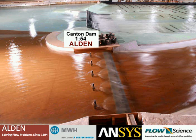We validated that model with a physical model, or better said, we tested our final design with the physical model, and you can see a picture of it here. It's a fairly large model, and this might go back again to what some of the previous speakers have pointed out. It's much easier to make a change to a numeric model than to break out concrete in one of these physical models and test a lot of different alternatives there. So ideally you try to test as few alternatives as possible in a physical model just because of the high cost of doing so.